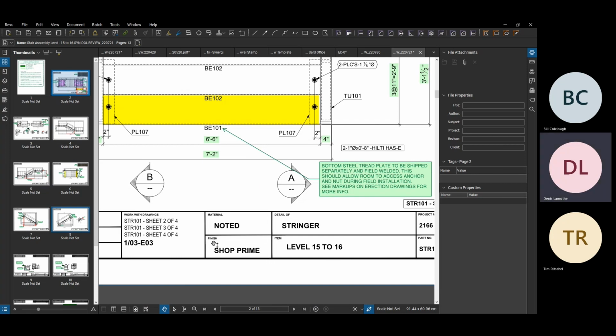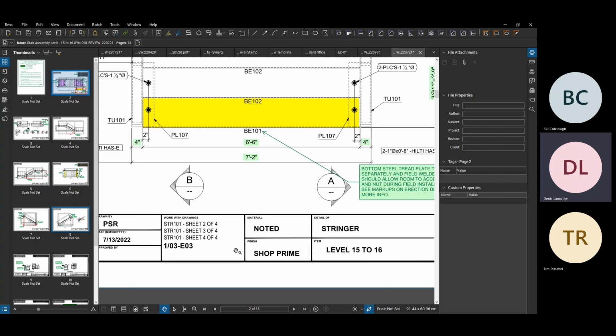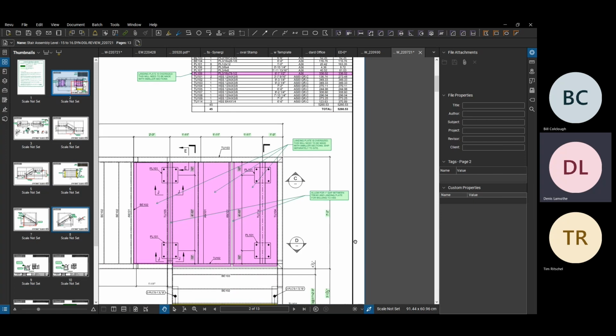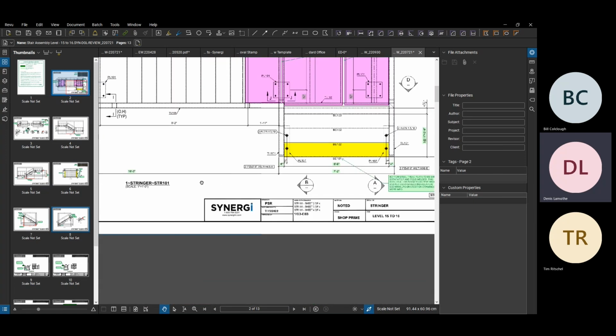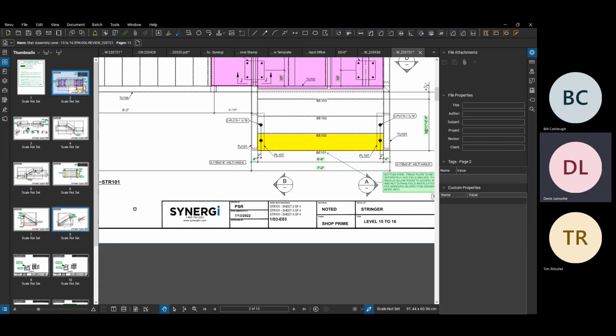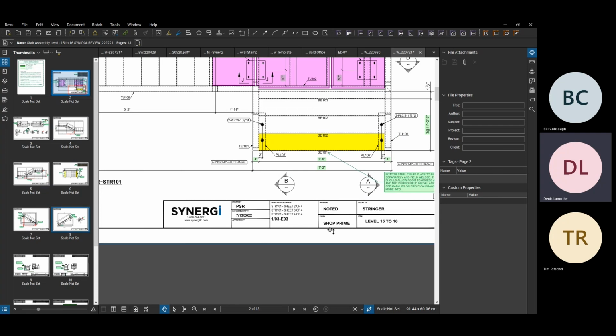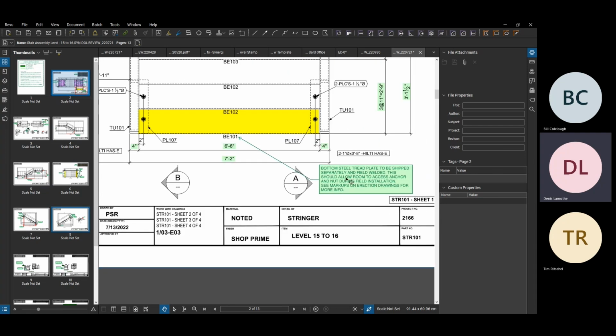If that's the case, just say in the finish, or materials, as noted, and then add a note somewhere on the page, probably near the title block, where you can list out in more detail what the finish is, like shop primer finish followed by powder coat, whatever, so vendor name, number or color, any of that information.